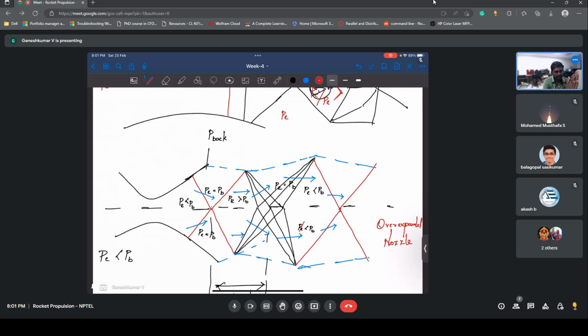The basic understanding lies there: if you have supersonic flow, in the convergent portion the velocity is going to decrease, and in the divergent portion the velocity is going to increase. That is the basic thing you need to understand. I don't know about cold boosters, but it can be because you don't need a very high velocity at the exit. So they will just converge it, and they may not even reach Mach 1 at the throat. They may not require that or something like this.